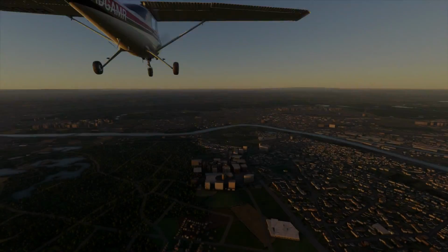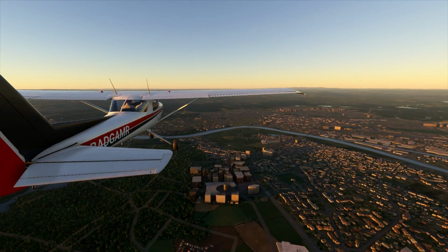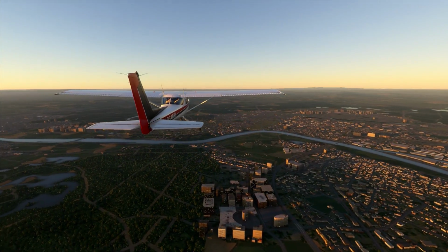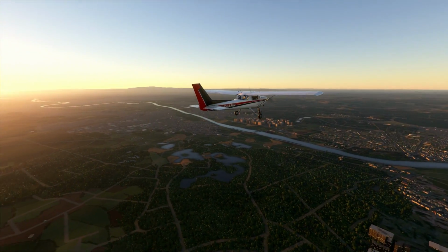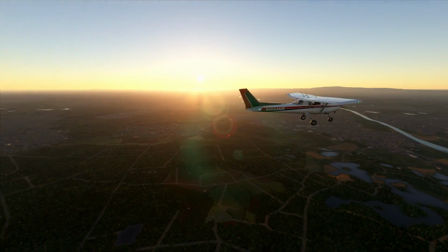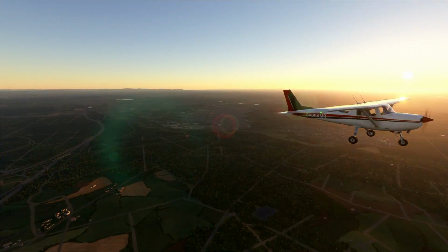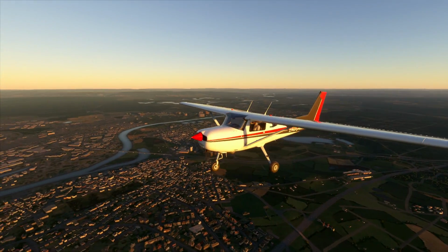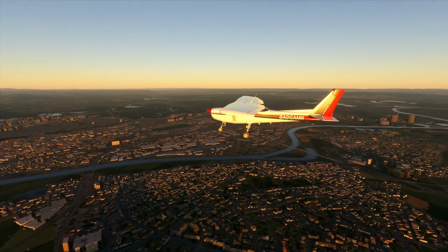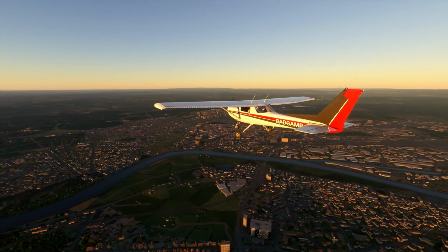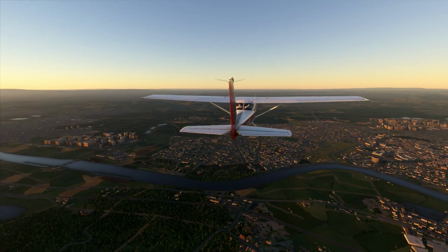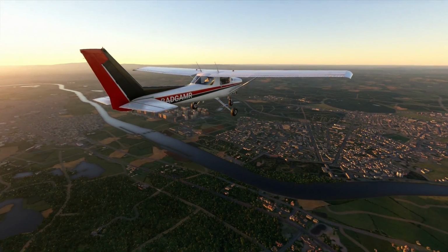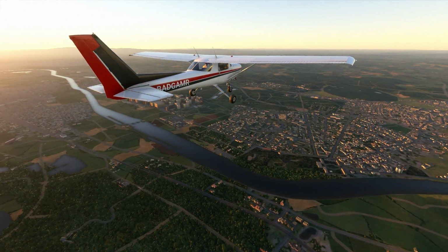Before we wrap this up, I want to take a moment to talk about the master switch bug in this aircraft. Supposedly, this bug is also present in the Cessna 172. There's a mod you can use for the 152 that corrects this issue as well as a myriad of other accuracy issues with this model, and I've linked to it in the description. Ideally, in the aircraft, you would use the battery master switch to supply the initial power to the aircraft as well as to start it up. Once the engine's running, you would then switch to the alternator master so that it can supply power to the aircraft as well as charge its battery, just as a car does.